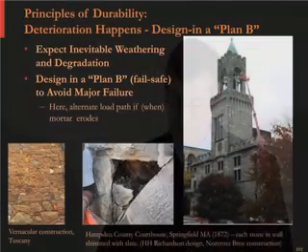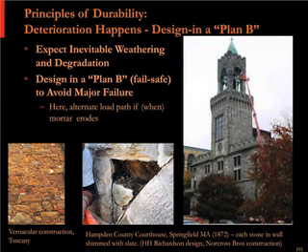And that really looks exactly like the vernacular construction you would see on basically every little village in Tuscany, which has houses that look like this at the right. So the stones are shimmed in. And so what happens is if, and I would say when, the mortar inevitably erodes, then there's an alternate load path. So then all these stones aren't free to pop out of the wall. They're still wedged into place like they would be with a very well-laid drywall.